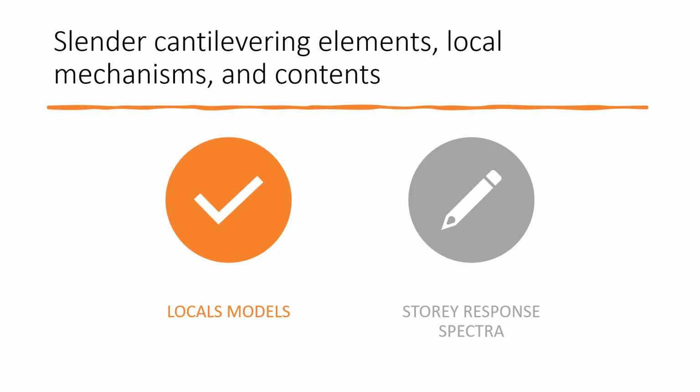In particular, they require the definition of an input by means of another response spectrum, which is not the response spectrum of the earthquake, but is the story response spectrum, which is filtered by the building response.